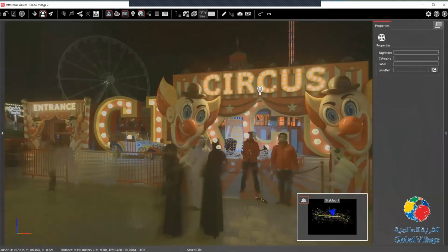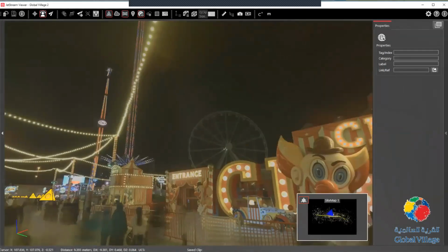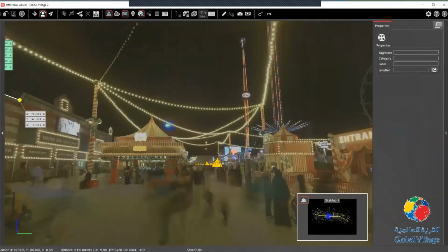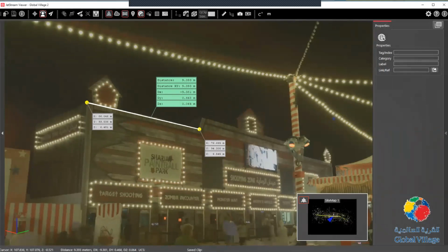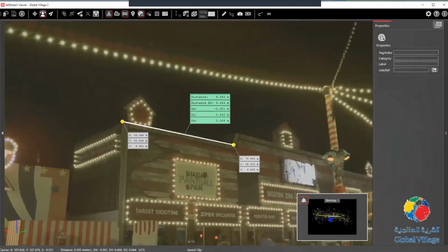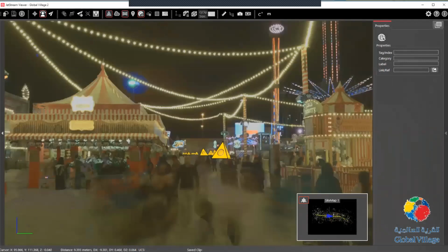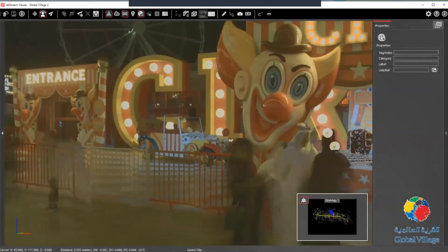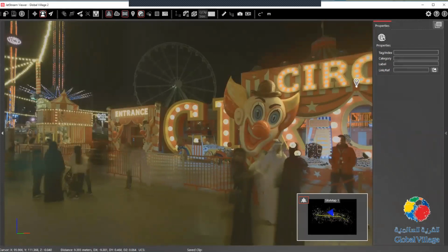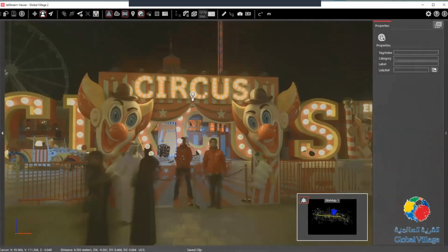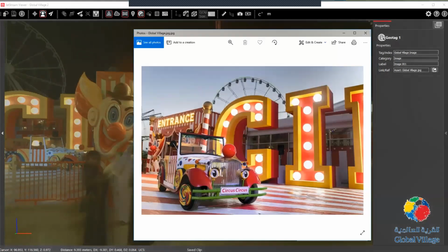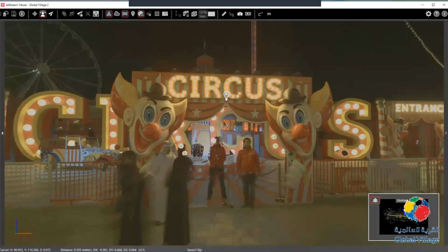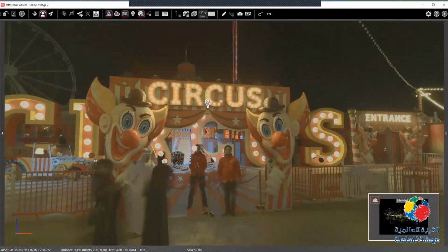This is a video which shows how the structure was measured, how it looks in 3D, and how you can take those measurements. Those are required for inaccessible areas where you want dimensions in terms of height, angles, and space. So all this analysis was done using a scanner called BLK 360. Along with this, it now allows you to have sensors. Once you have captured the area, you can have tags, and these tags can also be visualized.